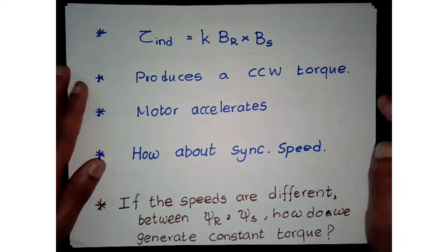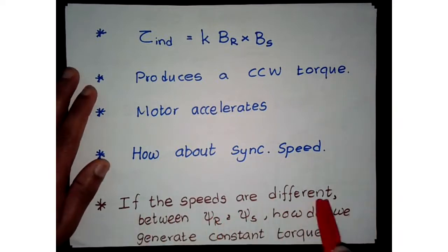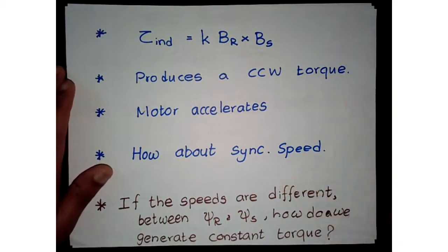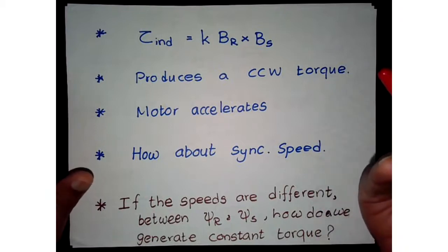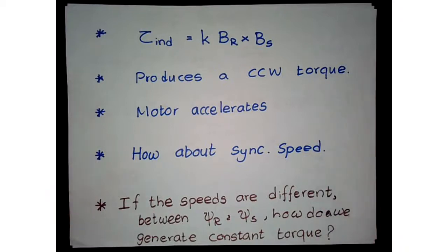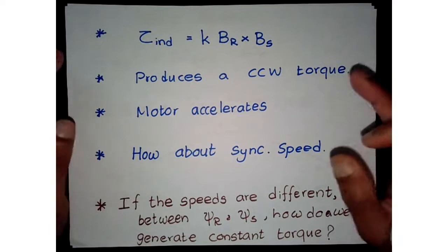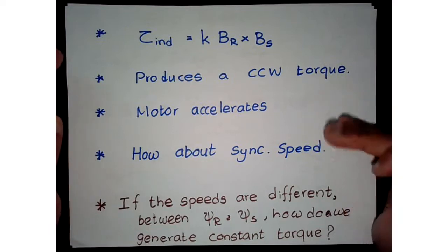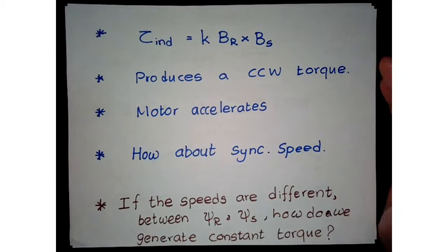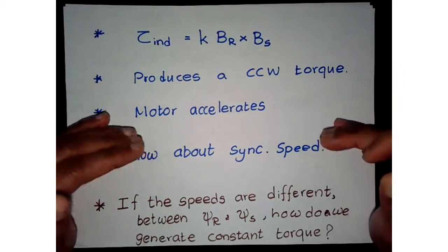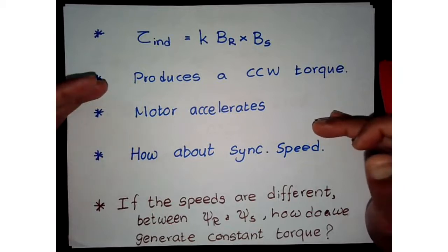All right. Now, one thing that we want to understand before we proceed, right? We said then there's going to be a field on the rotor, and we have a field on the stator, right? If you look closely in the induction machine, the stator field is operating at the synchronous speed, or the electrical frequency, and the rotor field is based on the speed difference.